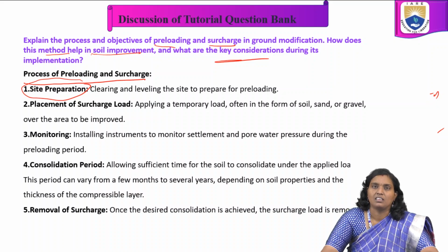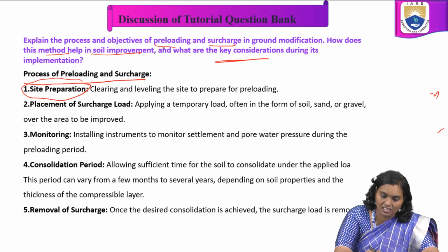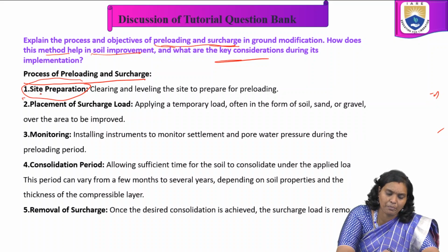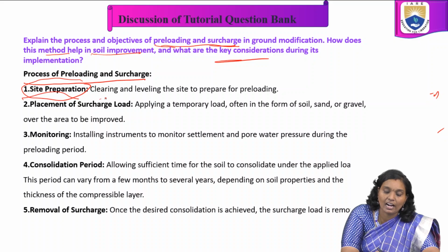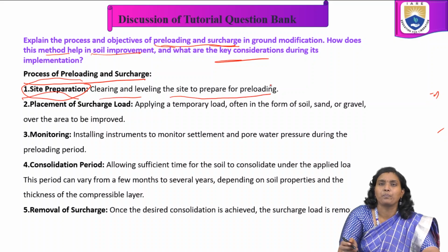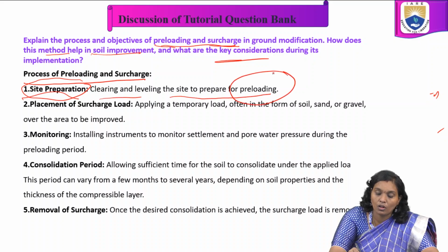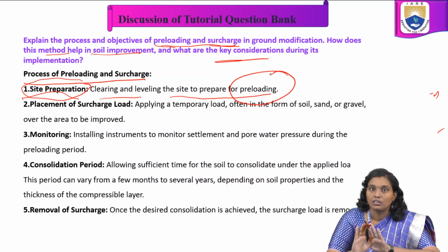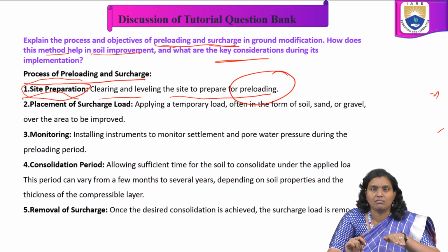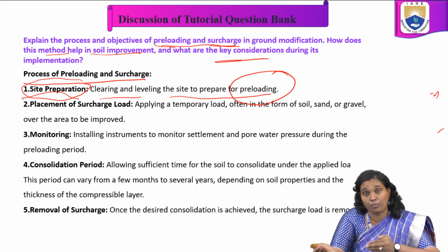So for preloading and surcharge, the first is site preparation: clearing and leveling the site to prepare for preloading. In preloading, we load that particular area wherever we require soil enhancement or modification of properties.